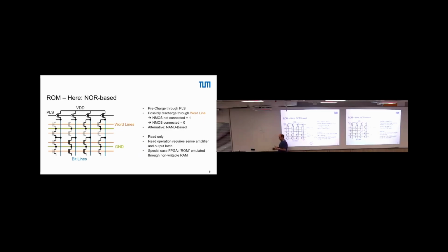Then we have the word line, maybe I take the orange color. This is until here 0. Now we switch here to 1, so we disconnect here. Then BL will slightly unload because of some leakage currents, but it more or less stays at VDD.